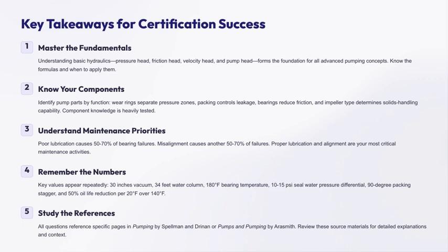Next, it's important to know your components. Be able to identify pump parts by their function, where rings, for example, separate pressure zones, packing controls leakage, bearings reduce friction, and the impeller type directly impacts solids handling capability. Remember, your knowledge of these components will be heavily tested.